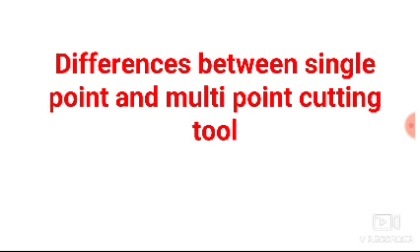Now the cutting tools are classified into three basic categories. The first one is single point cutting tool, the second one is double point cutting tool, and the third one is multi-point cutting tool. But sometimes the double point cutting tool can be referred to as a multi-point cutting tool. So we can broadly classify the cutting tools into two categories, that is single point cutting tool and multi-point cutting tool. So let's discuss their differences.